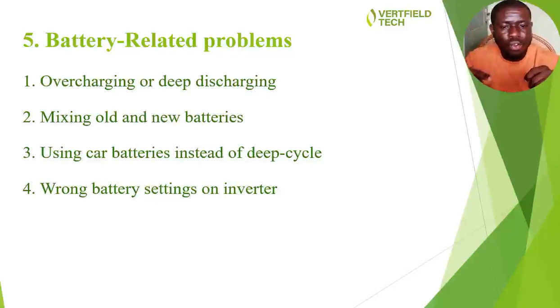Where the old batteries charge and stop and tell you it is full, that is where the new batteries will charge and stop and say it is full, while you will then drain it up to 100%. Means that the new batteries have not charged up to 100%, but you are draining the whole energy in it. Once you do this, how many cycles in a day, how many times do you do this in a year, your new battery is gone. That is why you are advised never to mix your old batteries with your new batteries.